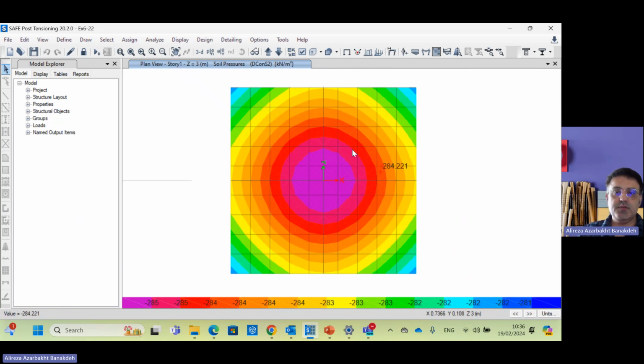So this should be compared with that one. In the example, it's not mentioned, so we don't need to do this for example 622. However, for the coursework, you need to have the subgrade reaction plus the soil allowable stress, the stress that it can carry. And this maximum stress should be compared with that one.